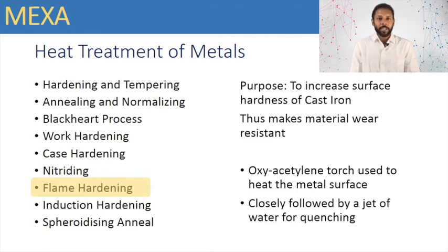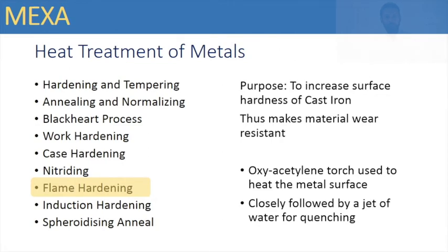A water spray closely following the oxyacetylene torch quenches the material, thereby inducing hardness. Care in operation of this process is essential because overheating must be prevented.